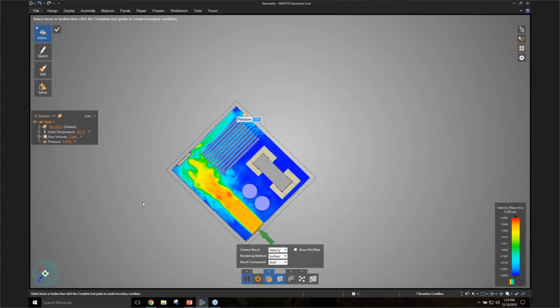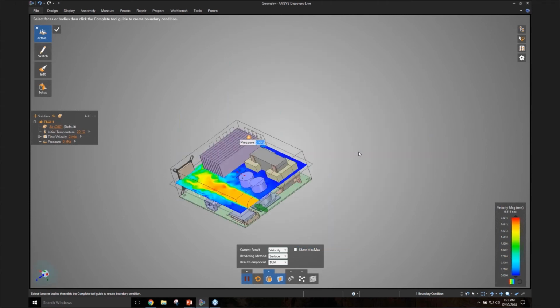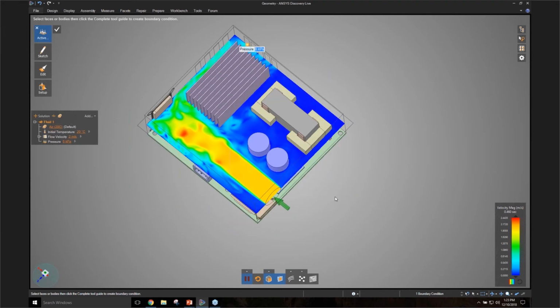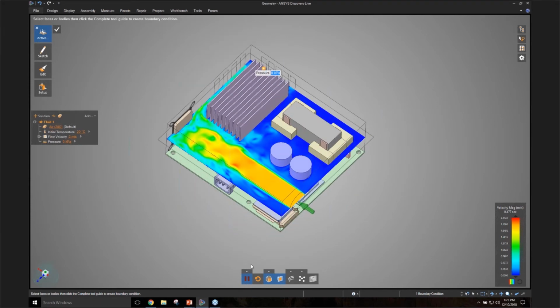By the way, if you want to get more resolution, or what those of you familiar with simulation may call more mesh refinement, the setting is very simple. You just have this speed versus fidelity slider. So as I move the slider to the right, it'll take a little bit longer to solve, but you'll be able to capture a lot more geometry detail, right?